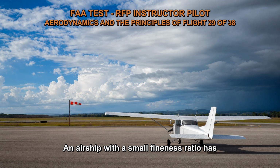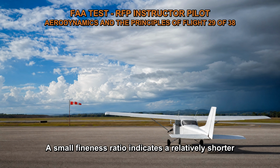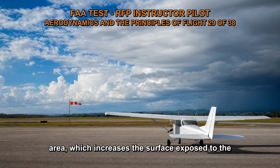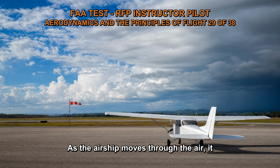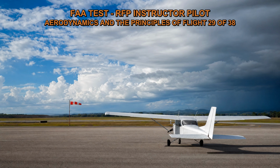An airship with a small fineness ratio has a hull form that will introduce more frictional drag due to the plump shape of the hull. The fineness ratio of an airship is the ratio of its length to its maximum diameter. A small fineness ratio indicates a relatively shorter and plumper hull compared to its diameter. This plump shape results in a larger frontal area, which increases the surface exposed to the airflow. As the airship moves through the air, it encounters resistance from the surrounding air molecules. This resistance is known as drag.